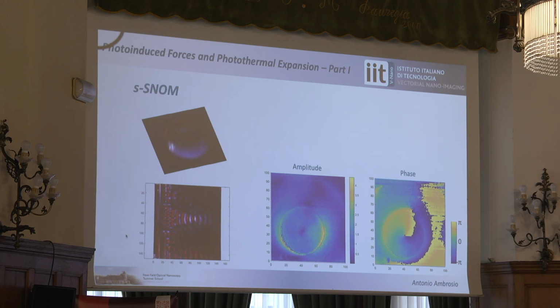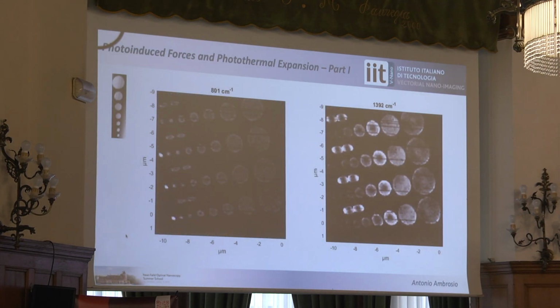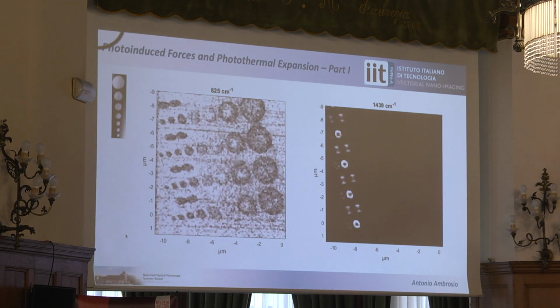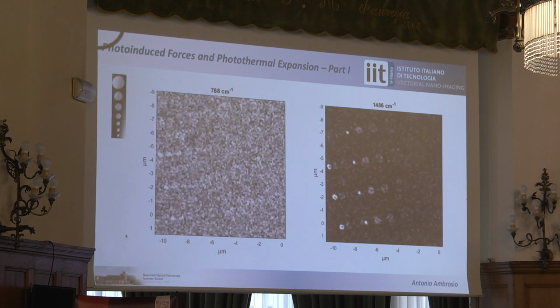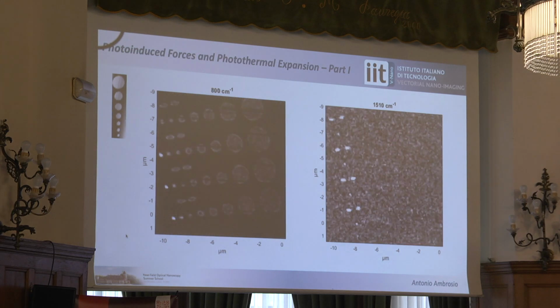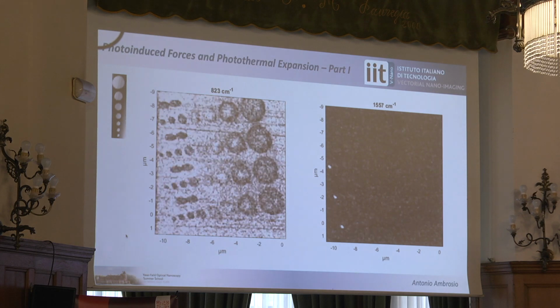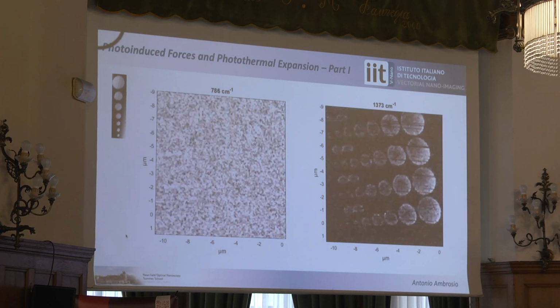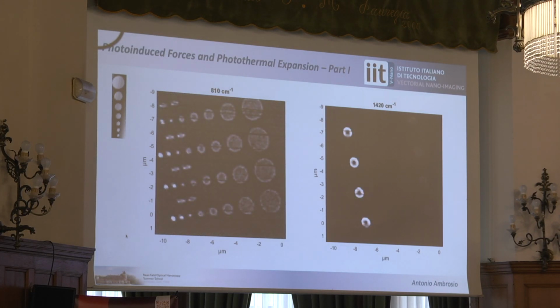Now, where I found this useful is in hyperspectral imaging. If you want to do a real hyperspectral image, where you keep the spatial stepping, so you do 500 by 500 pixels in an image, with scattering SNOM you would do that through nano-FTIR. But the SNOM has to handle an interferometer, do the Fourier transform, and you have an average on each single point.